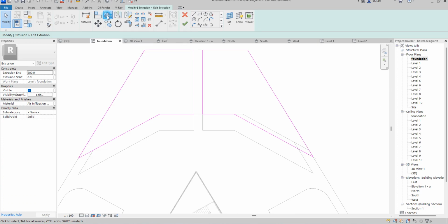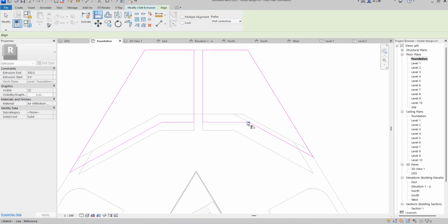So what will you do? Just offset from the front. So my offset is going to be 1.5, so people can stand here. No, offset without copy is what I want. Offset without copy, so that I'll be able to move everything I want to move at once. So you do it this way. Align this one first before you offset. So you can now offset.